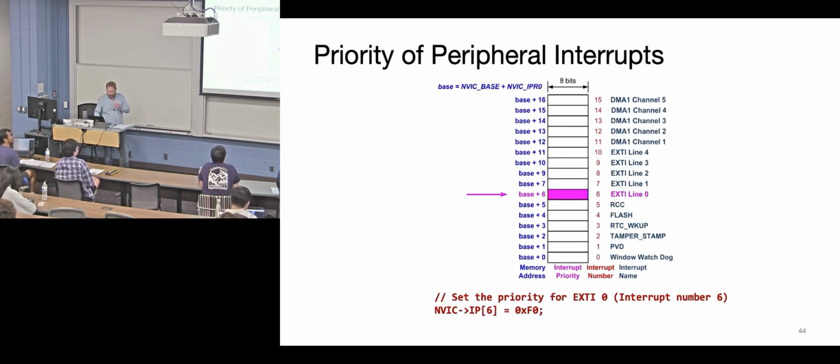All right, so you can imagine that since there's 8, they've allocated 8 bits even though you're only using 4. So now you have a memory address, and then each one of your interrupts you can define to have some preemption and sub-priorities. So you're basically going to write bits in these fields, and you can think about just having some memory address, and then you're incrementing by 1 for each byte of data.